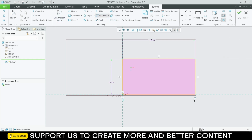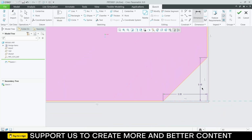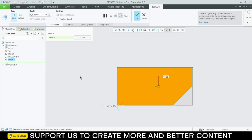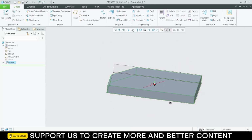Click on chamfer. Select these two edges. Zoom in. Click on dimensions. Double click on it. Type 5. 5 as well. Click on OK. Click on extrude. I will do an extrusion of only 2 mm. So type 2. Click OK. It is just a simple exercise for beginners.